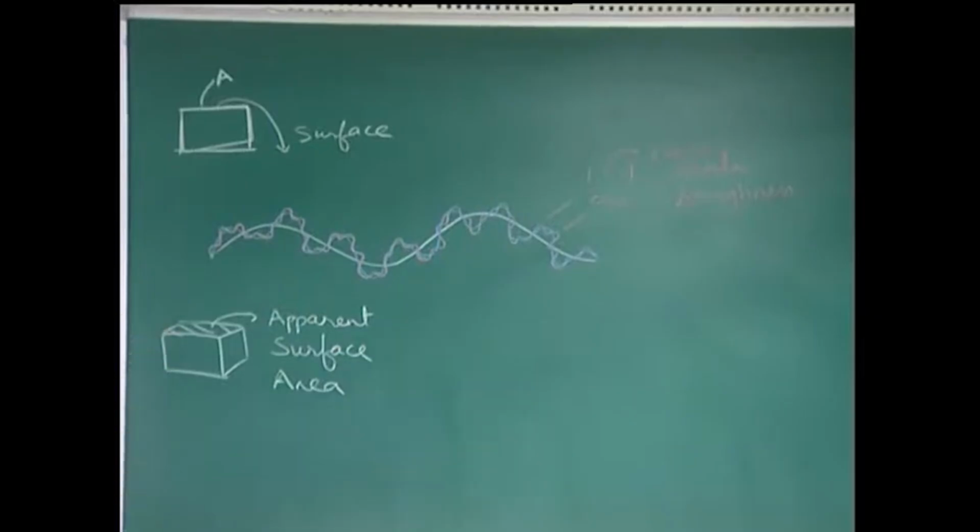That means I go to deeper and deeper scales and I find that the surface looks exactly identical at various length scales. If it were self similar across all length scales, then I would call it a fractal, but in typical systems you would notice that at least there are a few wavelengths present when I am talking about surface roughness.